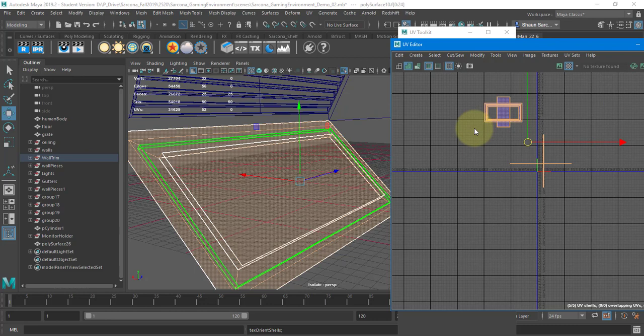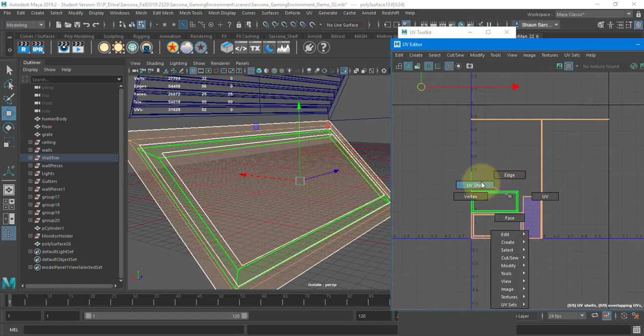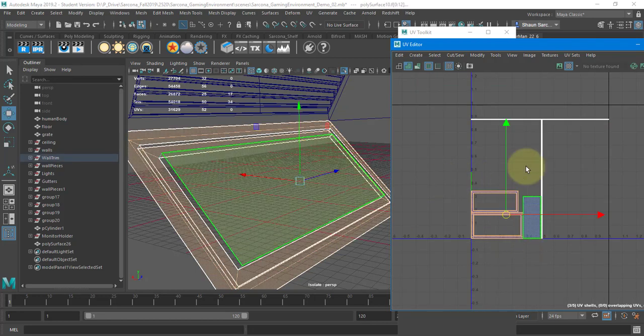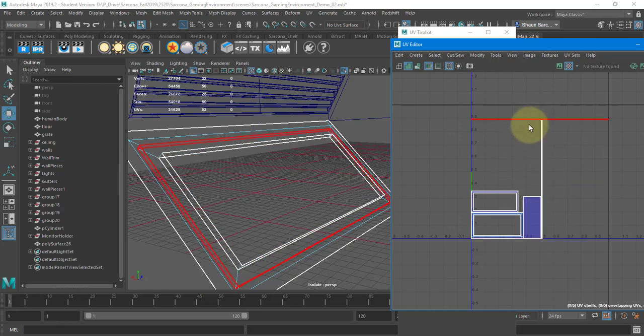The layout is going to try to make sure everything stays the same square size. Okay? So if I have pieces that are really thin and long, they have to fit inside that square, so it's going to shrink those down, and then everything else is going to be relating to that. Okay? So these pieces right here are pretty big, but they're pretty small on here. And then these ones are pretty long and skinny, and I'm wasting a whole lot of texture space.